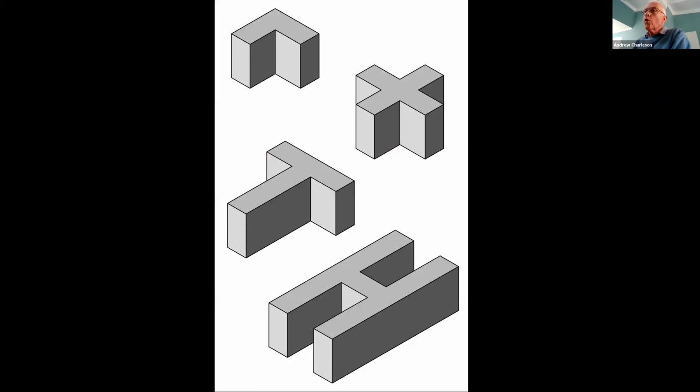What about re-entrant corners? Some of you may have configurations with re-entrant corners, like here, here, here, here, and here. Re-entrant corners are very popular among architects, but in earthquake regions, they cause all sorts of problems.